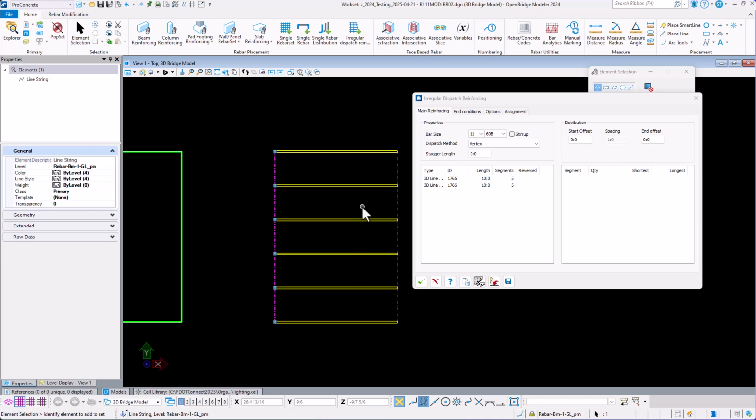So this can be really useful if you want to space bars at specific increments, like around anchor bolt blackouts or a drain pipe or something like that. You can draw your guidelines in with certain vertex spacings, and then your bars will automatically be spaced like that. And if you move those vertices, the bars will move with them. So that's the nice thing about this option here.